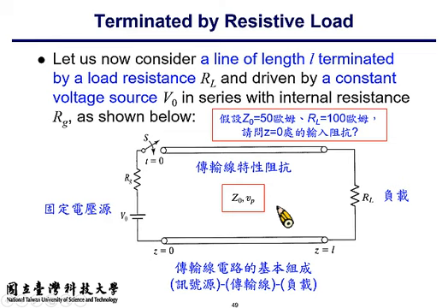On the other hand, the voltage over current ratio across the load, which is a 100 ohm resistor, should be 100. So you have impedance mismatch, and the result is that you will produce a reflected signal from the right-hand side. So there is a signal that we shall refer to as V minus.